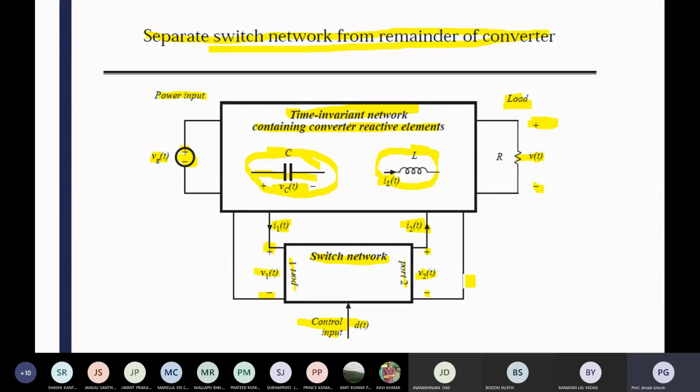So in the last method, if you go for that integration, all the values you can fetch over there. You are not directly going to approximate that value. We are calculating the state variables, and with those state variables you can implement any of the calculations. That is another well-known method. In that case we have to give some duty cycle, so you have to write down the average differential equation. Then you can simulate or compute it through MATLAB.